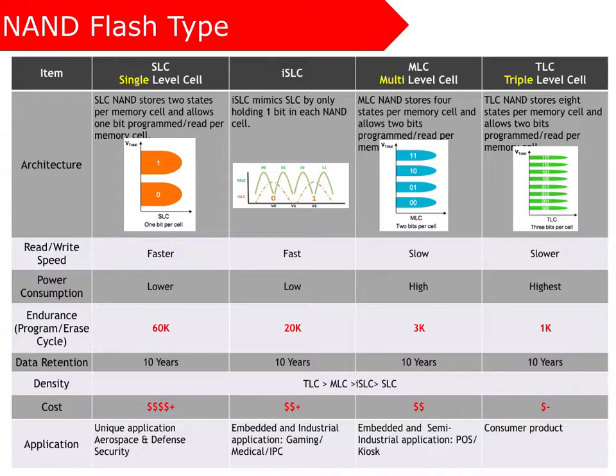Lastly is the TLC. This is the lowest level of the NAND flash category. Used purely in the consumer sector, it's the least durable, supporting 1,000 or less PE cycles. As InnoDisk's focus is only in the industrial field, we offer solutions in SLC, ISLC, and MLC categories, allowing you to choose the most adequate solution depending on your application.